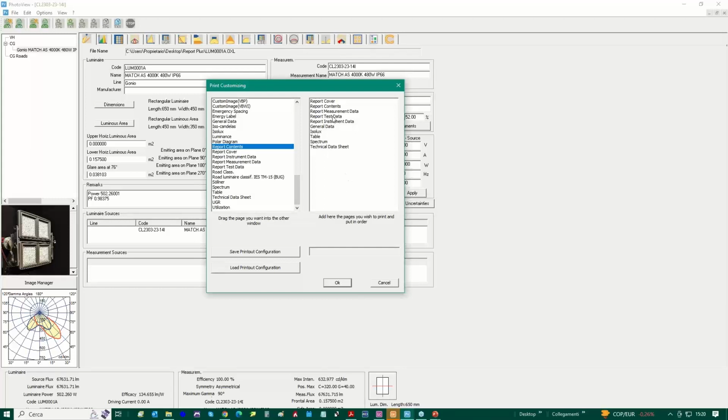about our report. So it is also possible to save the printout. For example, we do not use the same printouts and graphics for different luminaires. So a road luminaire has a set of printouts of its own, like a floodlight, like an interior luminaire. They have different approaches because they are about different areas. And so you may save different printout templates so that you don't have to define, anytime you need to print, the new set of printouts you want to use.